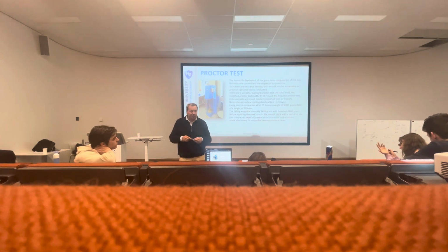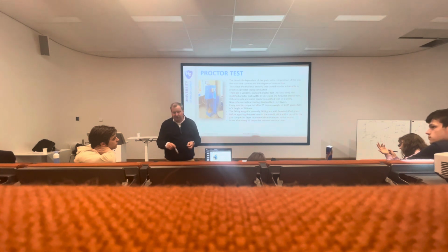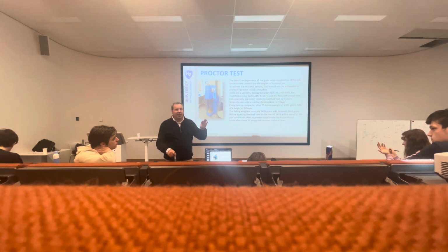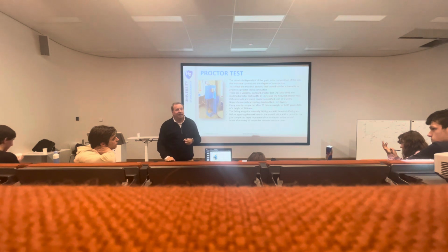That's what I was telling the Dutch students when I was in Saudi Arabia in the past, and we did their projects for highways, etc. To compact it, the moisture content should be exact. Because if it's like 5% less, you can't compact it, it's not good. Now, there of course it's a little bit dry, you just crush it open and 5 minutes later it's dry. So that's the advantage of those countries, let that be clear.